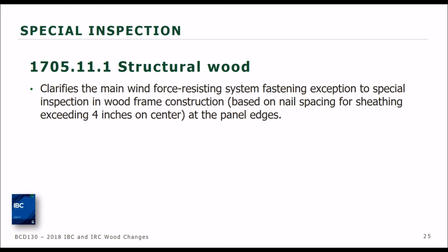What was clarified is, one, they now say specified fasteners, and it used to say fastener spacing of sheathing, instead of, now it says at panel edges. So specifically stating the panel edges, because you can have different spacing of your nails at panel edges versus your field nailing. So now specifically to the panel edge spacing.